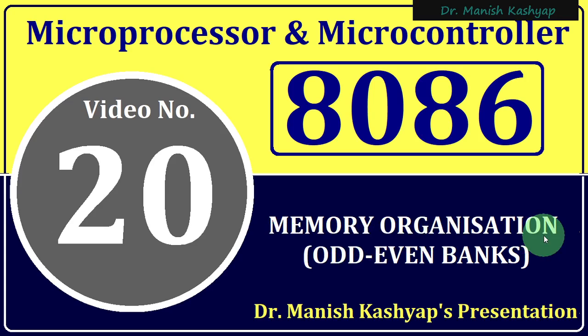in 8086. We will see that the externally interfaced memory, which is of 1 megabyte, is not used as a single chip. Rather, it is used as a combination of two chips of size half MB each, and they are organized into odd and even memory banks. We will see what these even and odd banks are, how they are accessed, how the address and data buses are connected, and when these signals are activated or deactivated.